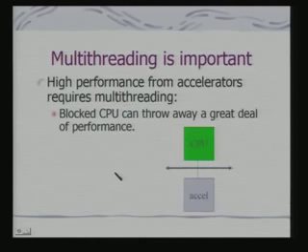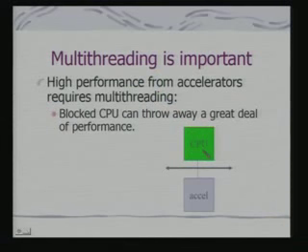Now, this takes us to the software aspect of the whole design. I told you that a platform based design is not just hardware design, but software design as well. The question is, if you have got the CPU and accelerator, how should the software be designed to manage these two things? Typically, these kinds of configurations would require a multi-threading implementation.